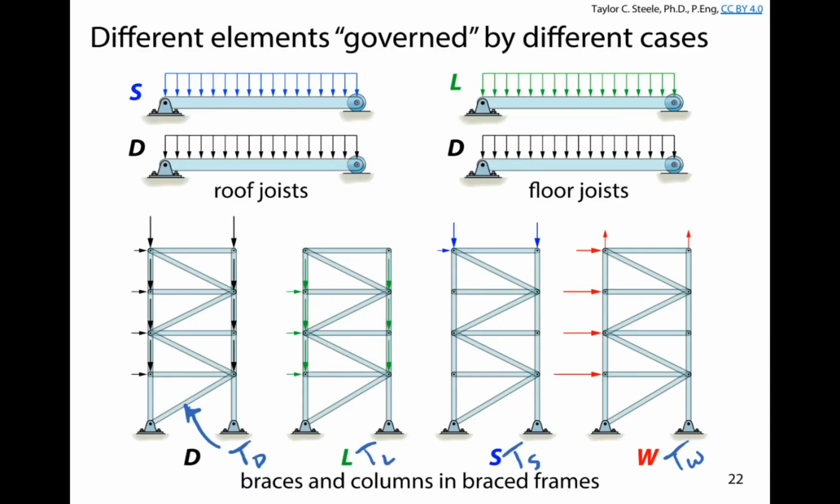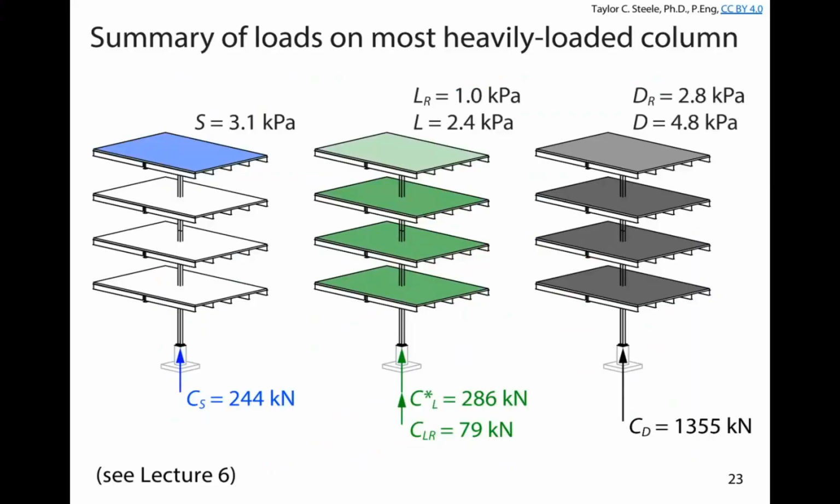We're going to calculate them using the specified loads that we calculate. Then we're going to add those effects together using the load combinations. Okay? You'll have an opportunity to ask me a question after I go through this with you. In lecture 6, for example, we're looking at the compression on a column that might come from snow, roof live, and dead load.